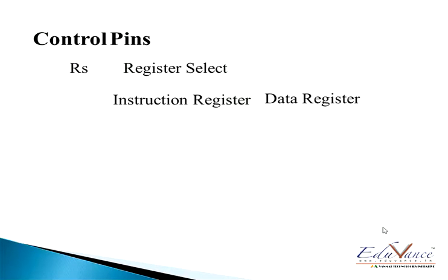The ASCII representation is 8-bit, and as we saw earlier in the pin diagram, we have 8 data bits. So both the instruction and the data go through the 8 data pins D0 to D7, but the register select decides which register the data is stored in, either the instruction register or the data register.